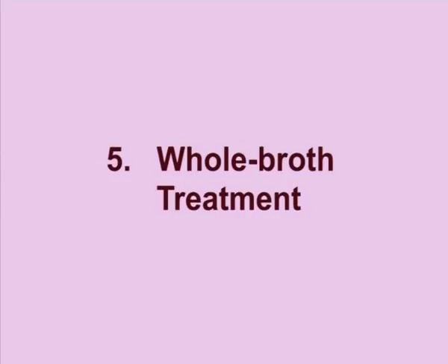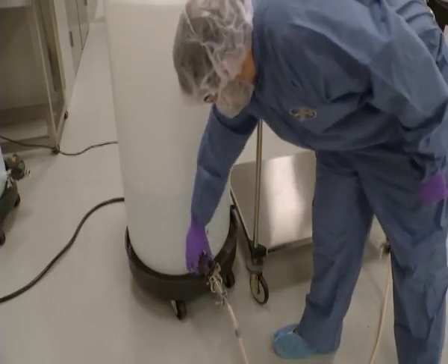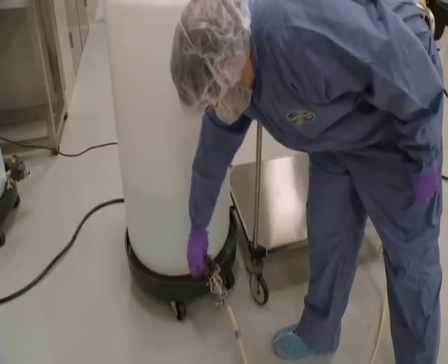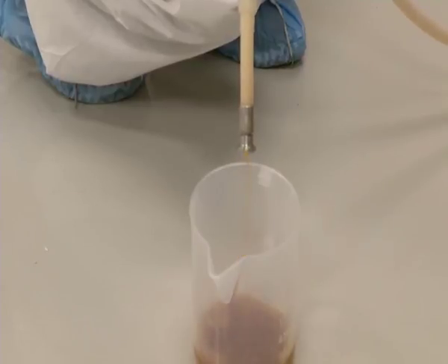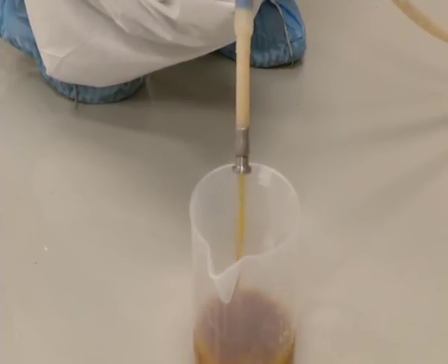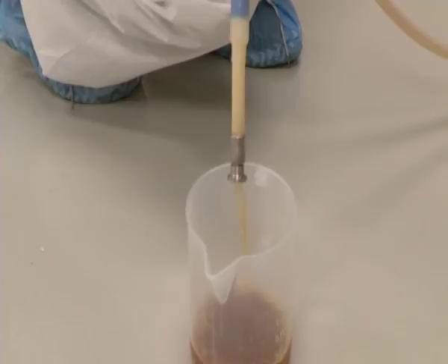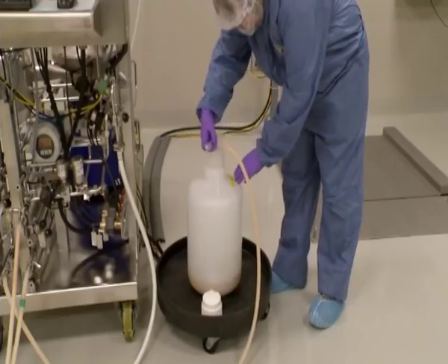Whole broth treatment. As had been indicated earlier, in some fermentation such as the acetone butanol fermentation, the whole unseparated broth is stripped of its content of the required product. This process saves the capital and recurrent expense of the initial separation of the solids from the broth.